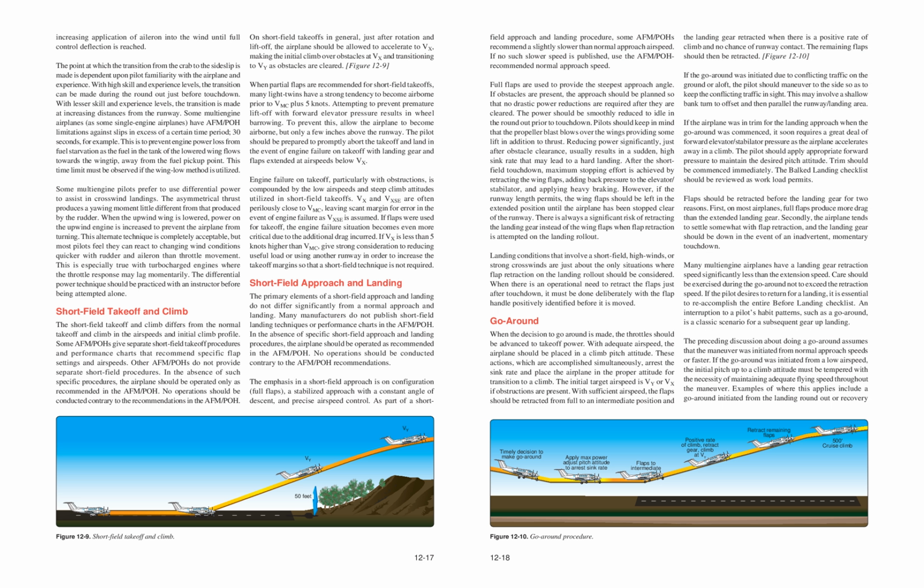If VX is less than 5 knots higher than VMC, give strong consideration to reducing useful load or using another runway in order to increase the takeoff margins so that a short field technique is not required.